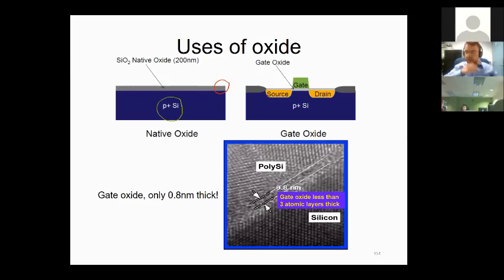And of course, by now, I'm sure you already know that when you find a wafer just sitting all by itself in a clean room, that will not be an immediate silicon wafer. There will be very likely a native oxide. It's not too thick. Actually, it's going to be up to 2 nanometers or 3 nanometers, less than 5 nanometers for sure. But there will be a very thin layer, and it's going to be residing there, waiting for you. All right. So that's the first oxide. It's just natively grown oxide. It's just grown by itself.